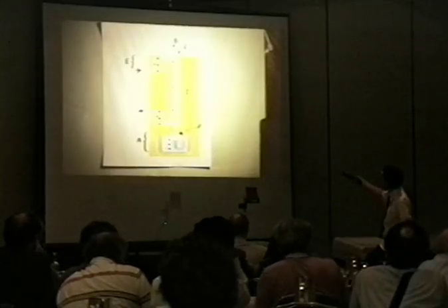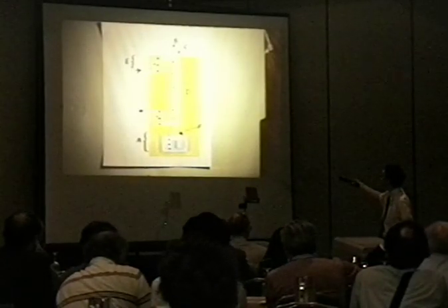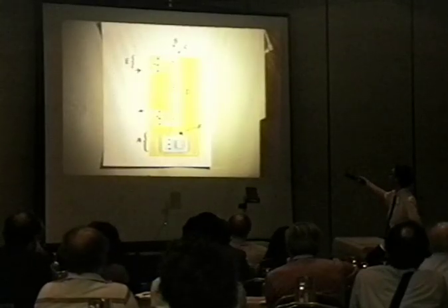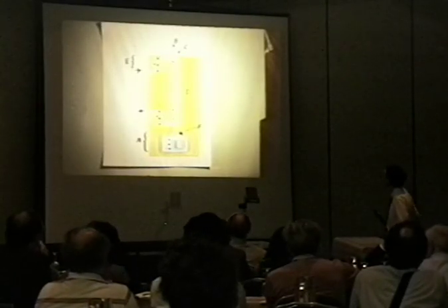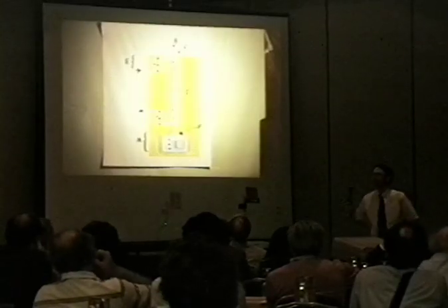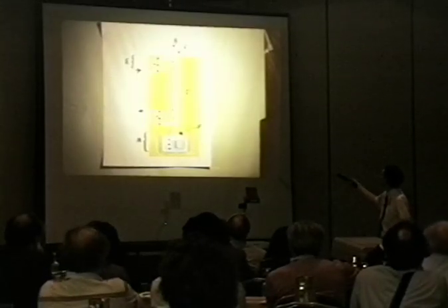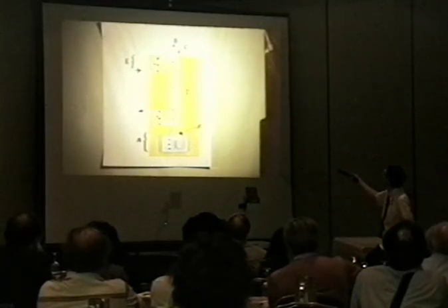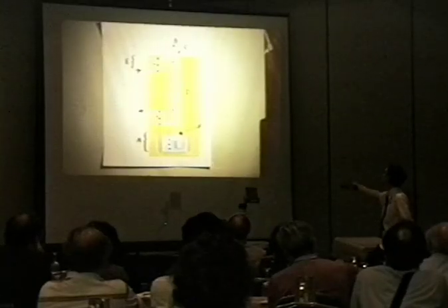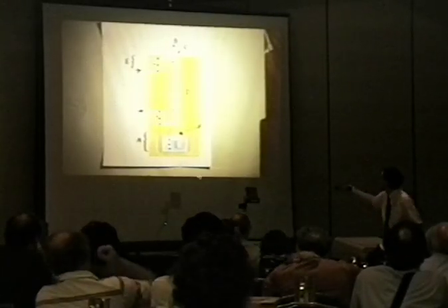I have a central column. This is actually 40 centimeters from there up to this glass wool plug. I then pack some aluminum oxide for surface condensation sites, to increase the bubble plates, for the engineer types. And then above that, I have a recombining material. I have another plug there. There's actually a Tygon tubing that goes up and around to prevent the hydrogen from going up, or the heat just chimneying out.